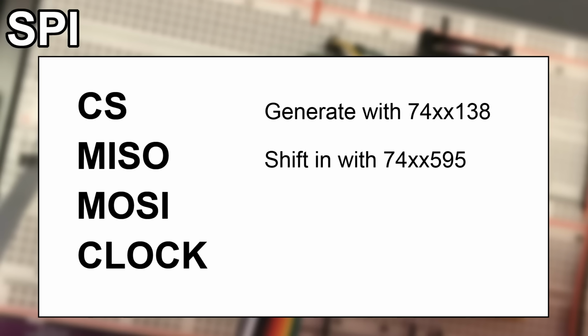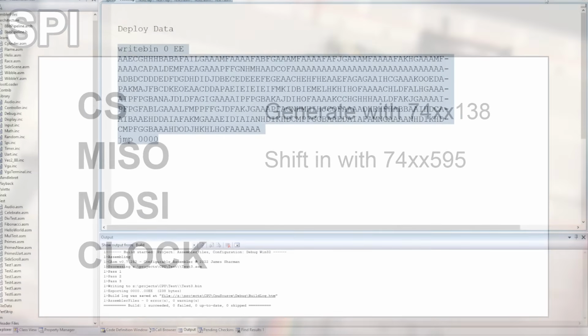But I think we've got a problem, and that problem is with the clock. You would have noticed when I made the changes to the code there, but I didn't fix the MCP version, and that's because I can't with the circuit as it stands. We've hardwired the relationship between the clock and what we're expecting our internal data collection to do, and that was one of the pieces of code that changed between mode 0 and mode 1. So we need to address that before we move on.